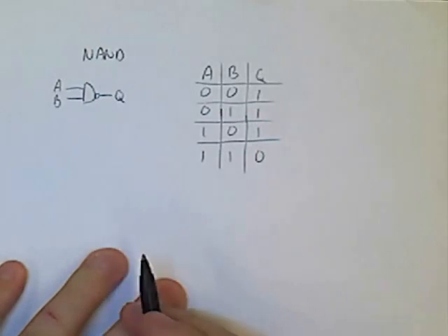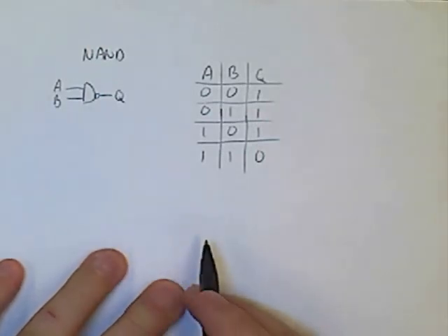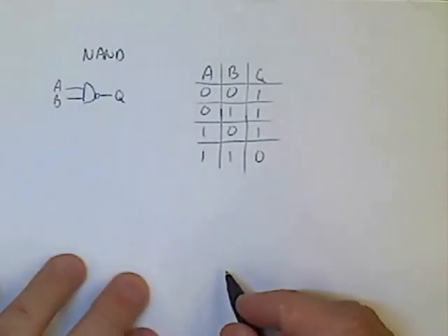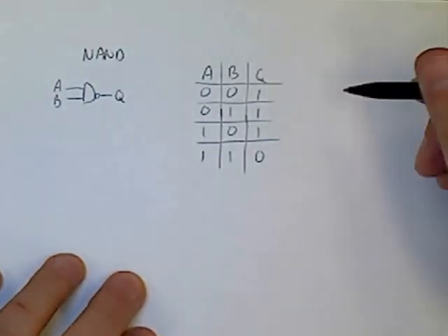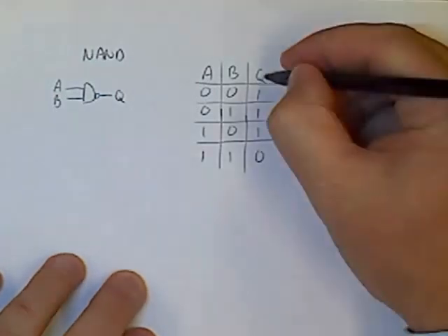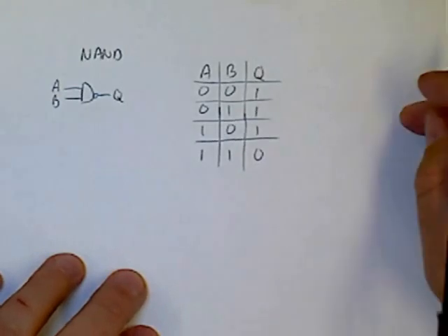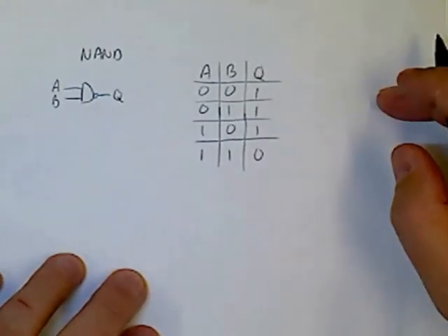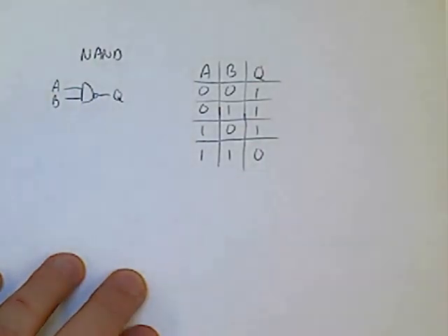Now, a very important gate to create from this is what we call the inverter. So the inverter only has one input, and it changes it. So if the input is 0, it makes it a 1. If the input is a 1, it makes it a 0. Okay, so that's where there's a hint as to where its name, its operation in its name. That is, it's a NOT gate. So a NOT gate means that whatever the input is, the output is not that.